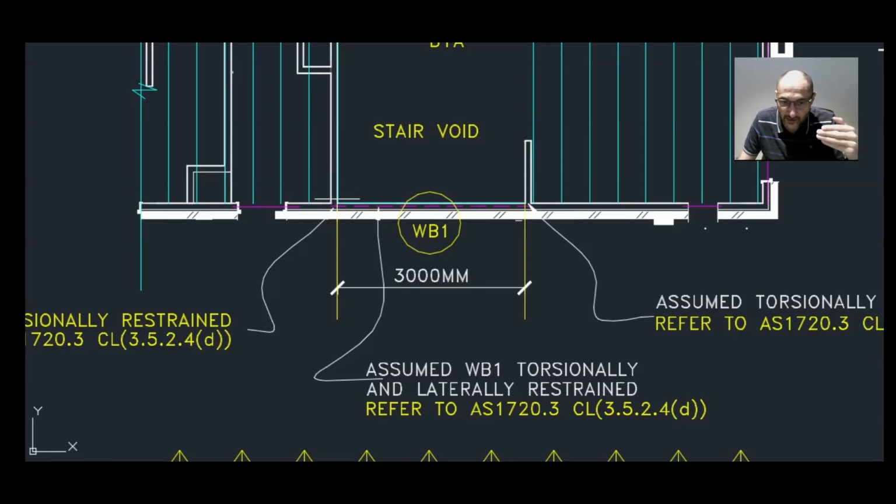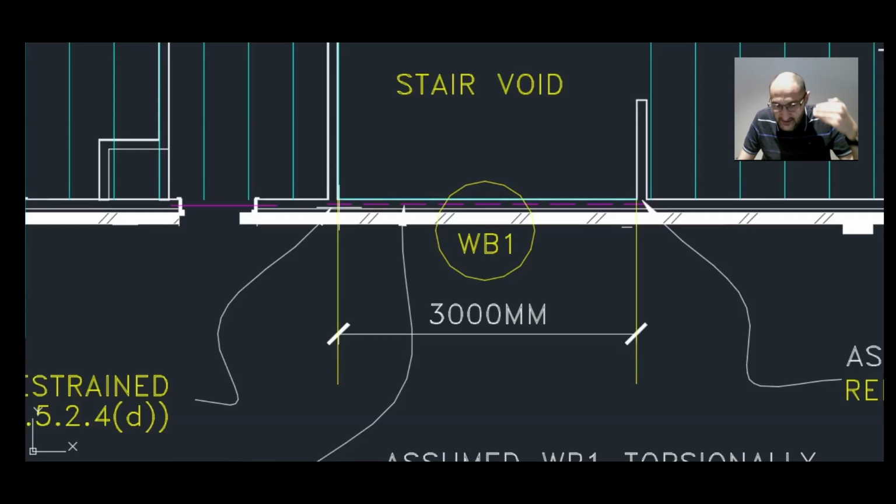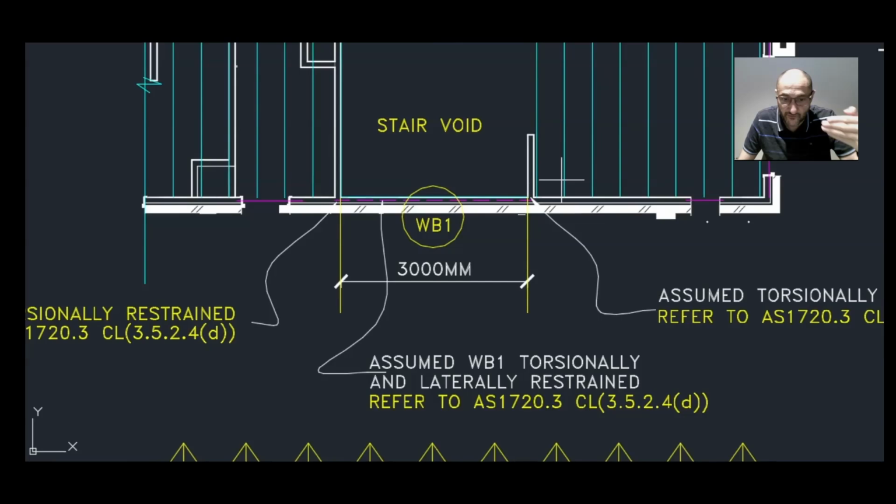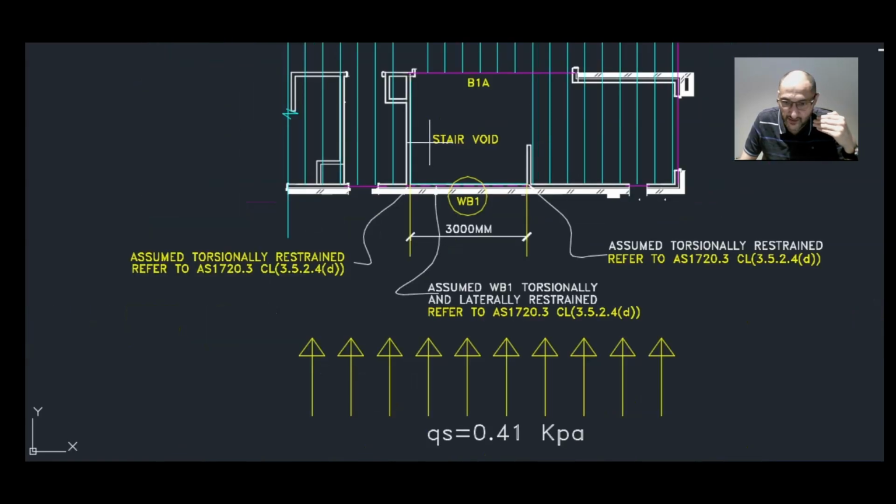Say we have a 90 millimeter wide angle to be the width of the wall. So the vertical height of the angle is bolted to the face of WB1, and then the horizontal leg can be bolted onto the top plates of this cross wall here. And I would also make sure that the cross walls are also braced to provide rigidity in the bracing elements.